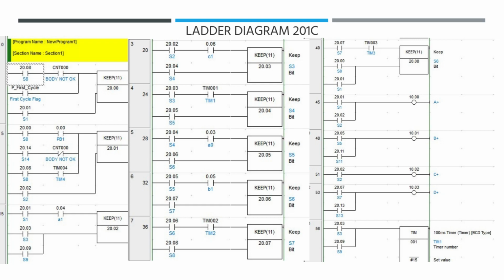After retracting cylinder A, cylinder B will extend. After cylinder B extends, it will delay for 3 seconds. Then it will retract. After it retracts, cylinder D will extend, and then it will activate a timer for 3 seconds, then it will retract. That is for the correct position.